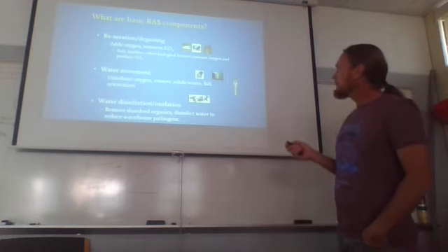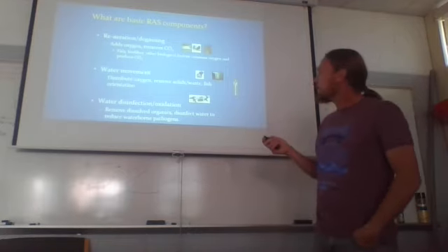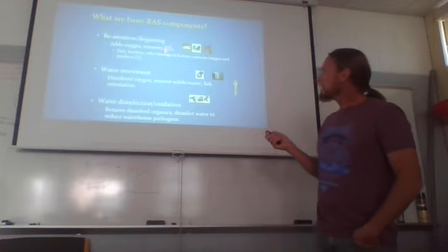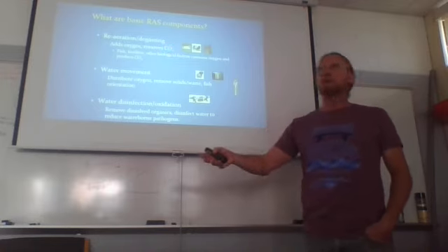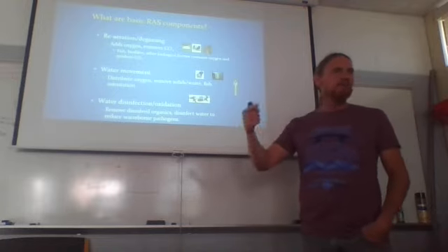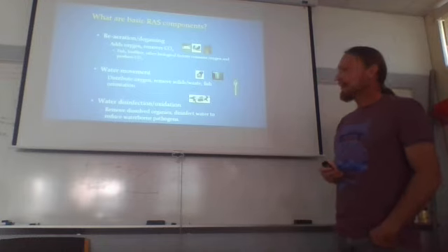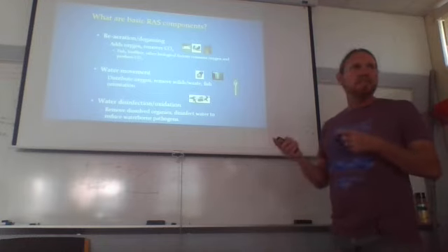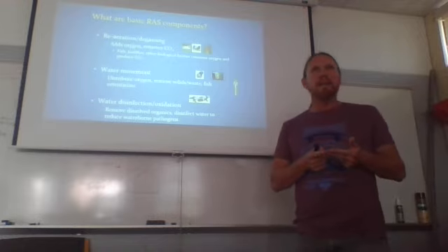Degassing. The act of degassing has a couple of benefits. First of all, as CO2 starts to build up, you can provide a way out for the CO2, but it also can gas the water, can also take on oxygen. And this is basically the idea of aeration. You're creating here just a high surface area between air and water. And one way to do that